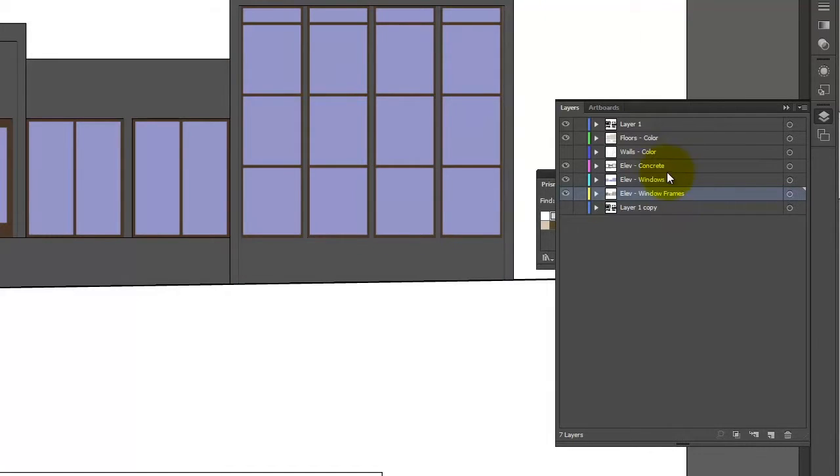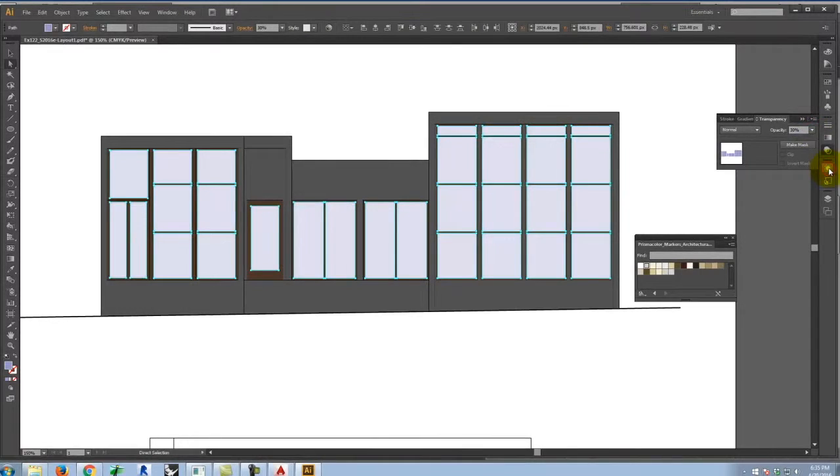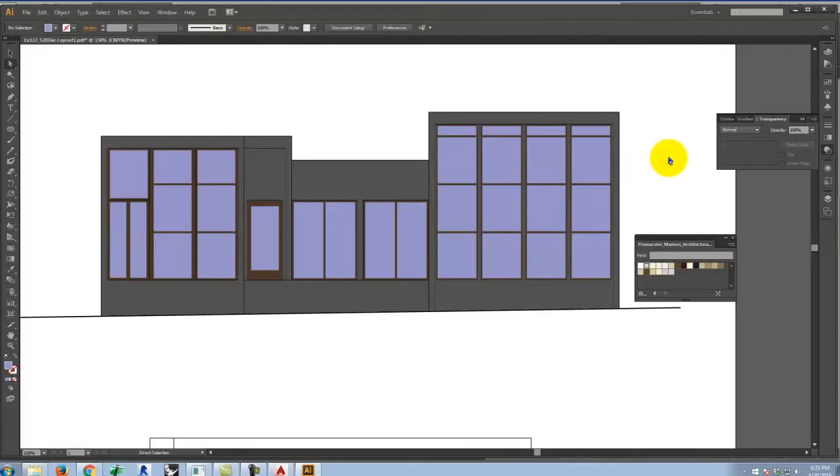So if I were just leaving the colors, maybe I would select, say, the windows, for example. I'll select all the windows. And then I adjust the opacity down maybe to 30% or 40% or something. So they're not nearly as strong. And I do the same for the other colors. Okay? But that might not be the most realistic set of windows either. And so maybe I want to use a different strategy.